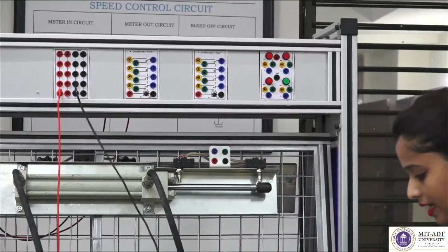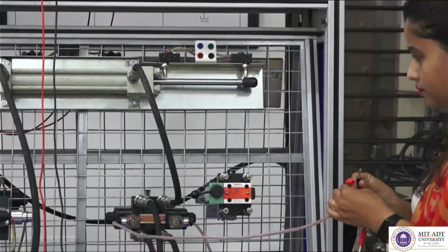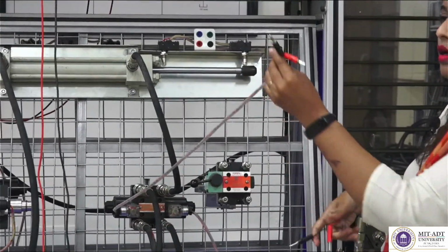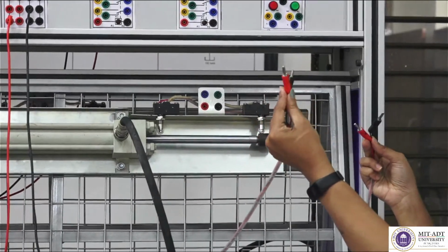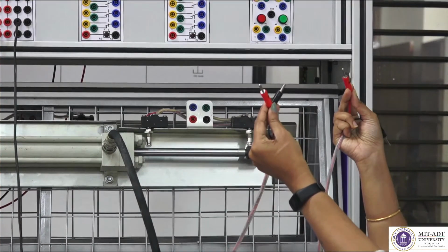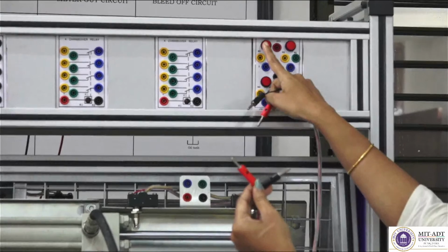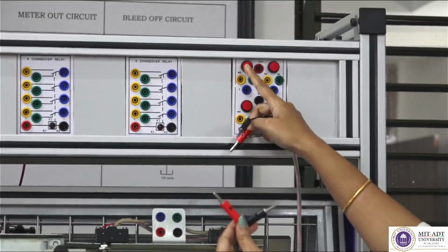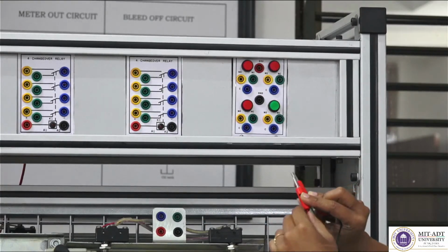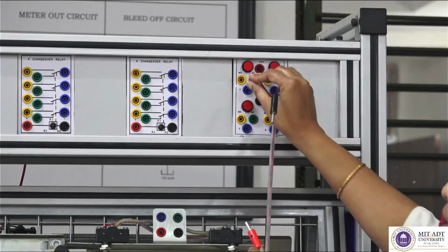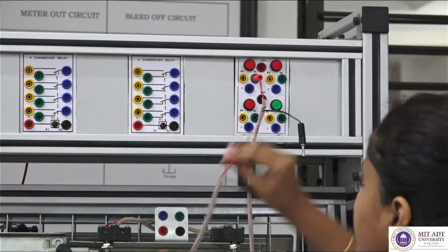Okay. Once again I am going to tell you how I did the connections. I have red and black from this solenoid, I have red and black from this solenoid. What I am doing is, I just wanted to use this red color non-latchable push button. So I am putting both the red colors into NO and NC. NC is green color, so I am pressing it over here. This is NO, so I am putting it over here.